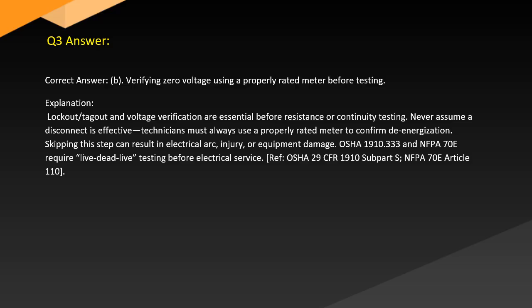OSHA 1910.333 and NFPA 70E require live-dead-live testing before electrical service. Ref: OSHA 29 CFR 1910 Subpart S, NFPA 70E Article 110.